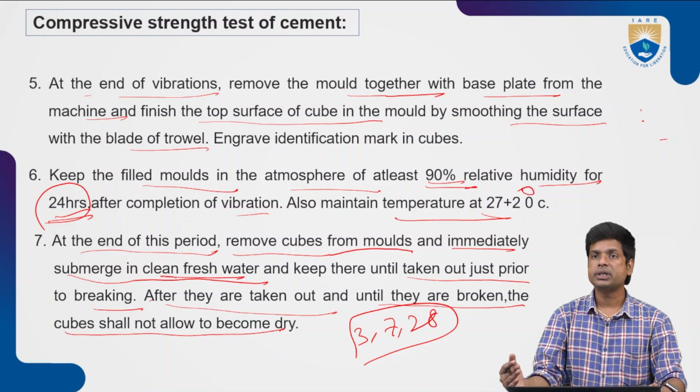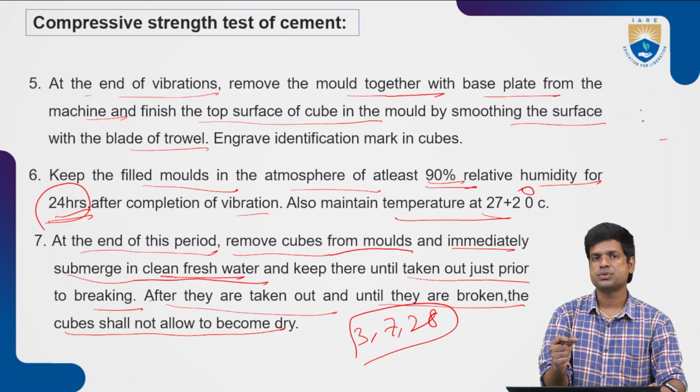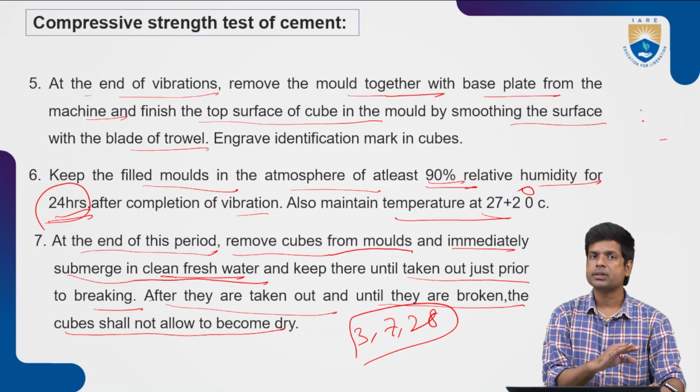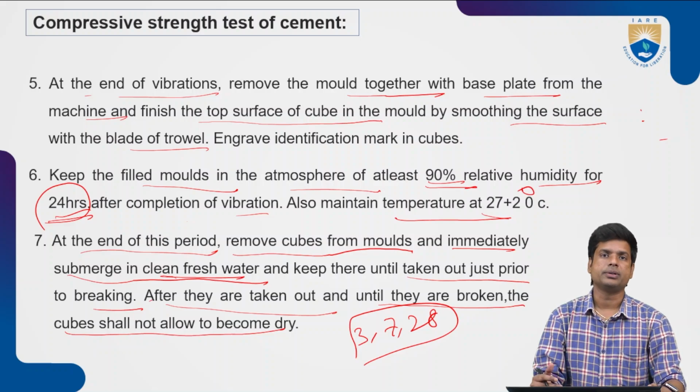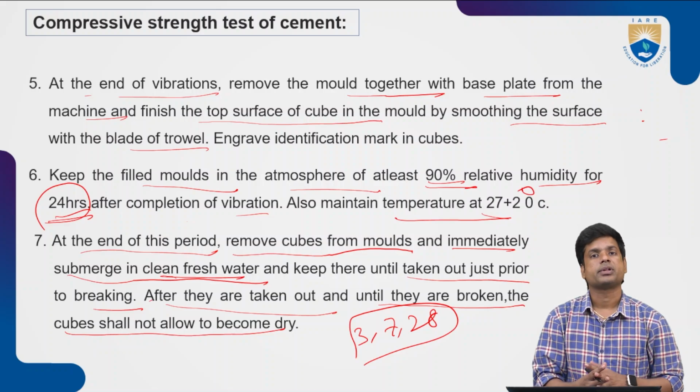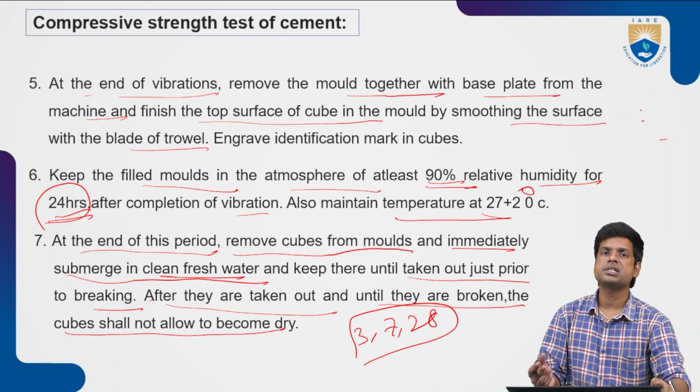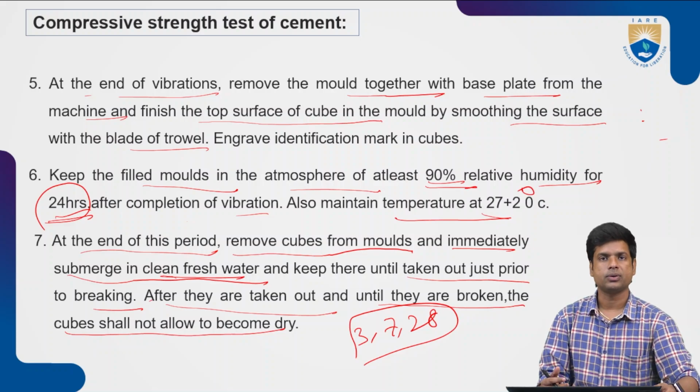It should be continuously cured, and we should not let the cube dry; continuously apply moisture in the curing.